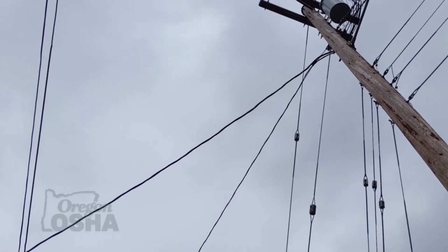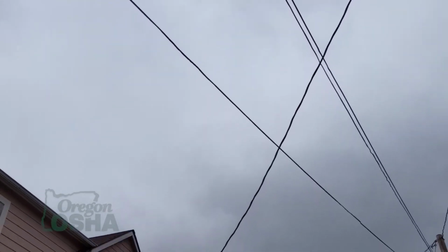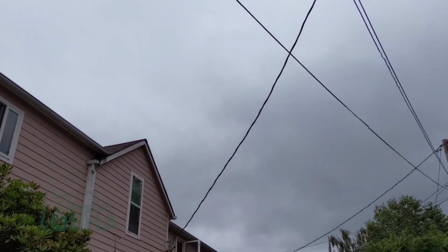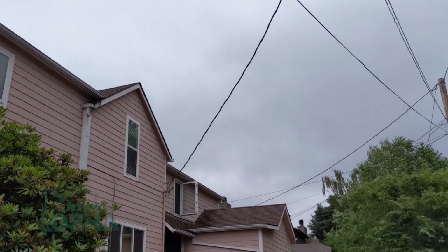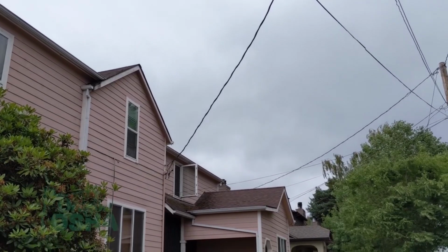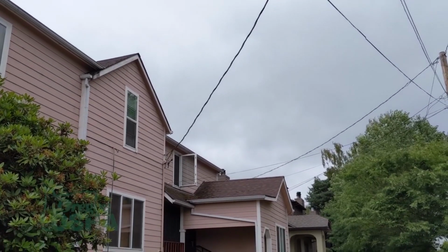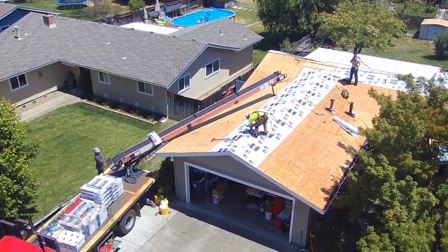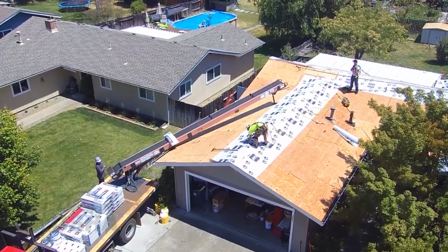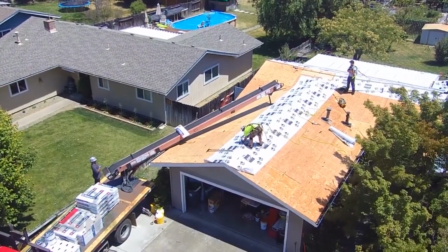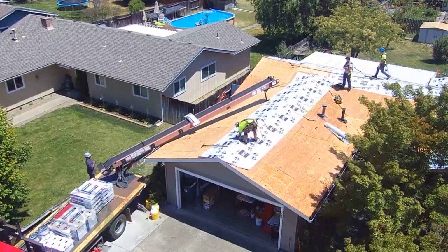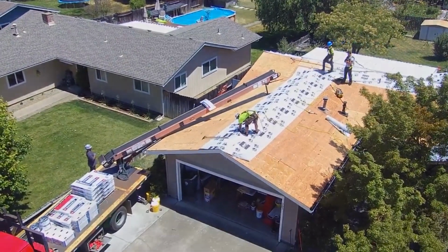One of the things that we also look at as far as the safety of a job is the power lines. If there's a power line that's running right up close to the roof, or if it runs across the roof, if it's anywhere one of our employees could actually touch it or bump into it, then we have the power company come out and put their protective shrouds over the line. So really all aspects of roofing have an inherent danger to them. It's just making sure you get set up to give your employees the best safety practice possible.